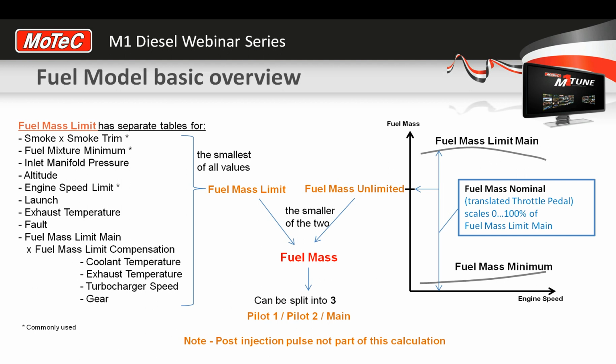The ECU will automatically limit the amount of fuel based on what it calculates the lambda is going to be. It actually uses the lambda estimate channel to do that. That's the channel we explained, if it wasn't last webinar, it was the webinar before. It doesn't use live lambda for this because that's too delayed.